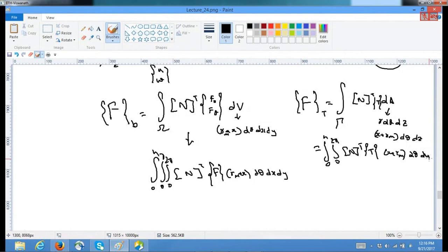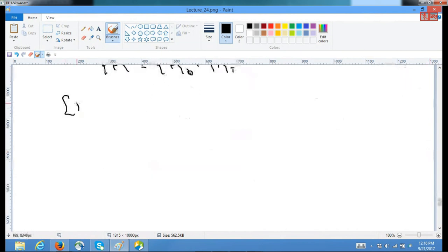So our total force vector, this is F. So our total F is nothing but the sum of body forces plus the sum of the traction forces. Now what we have done is, I have determined how to get the K matrix, and we know our U, and then I have also shown how to obtain the nodal RHS vector or force vector.